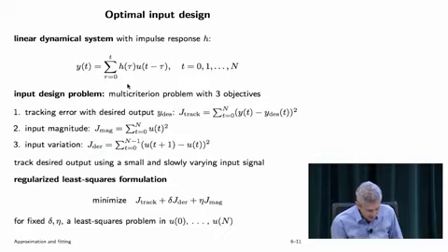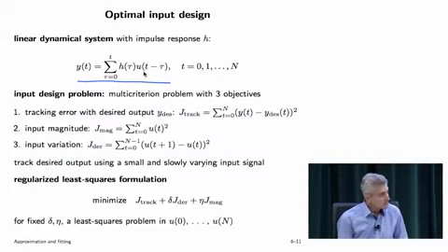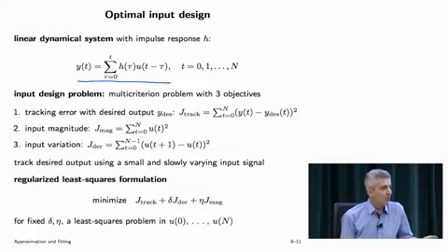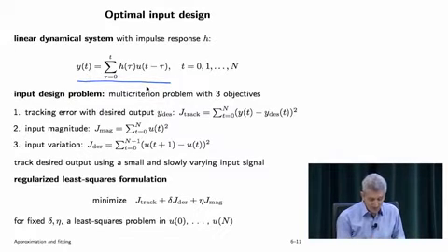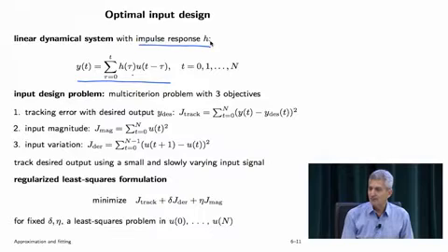Here's the idea. I have a convolution system. So I apply an input, u, a scalar input, at various time intervals. It could be a force I apply to something. It doesn't matter what it is, right? And something I call the output is a convolution of the input with some convolution kernel, or in EE dialect, that's called an impulse response.